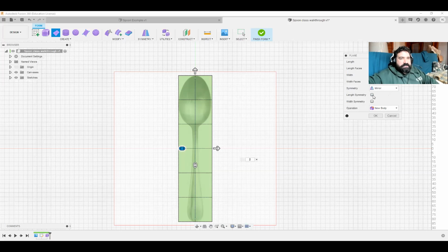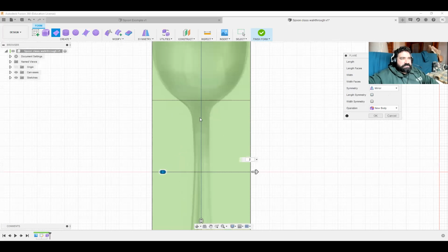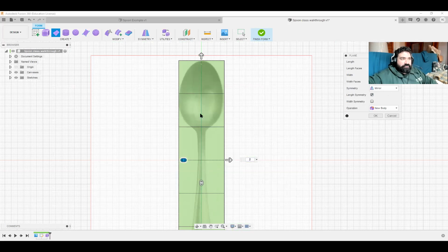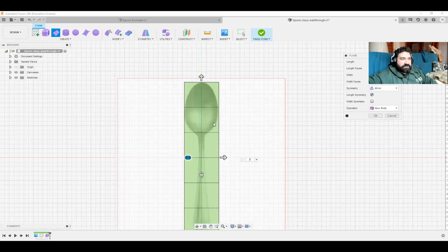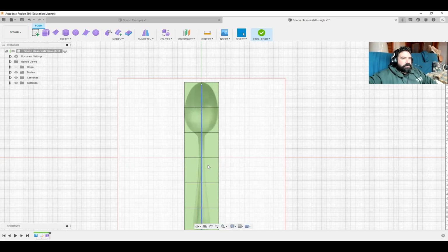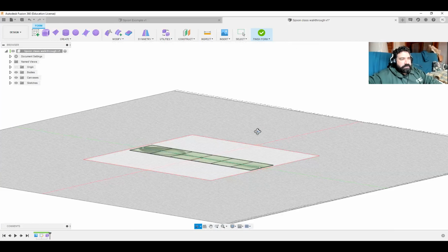The selection there is length symmetry. When you select that, if I zoom in close, you can see that center line is just a line like anything else. If I select length symmetry, that becomes a dotted line, just like a construction line, because what that's showing is now it's green. It's showing that's the symmetry. Across that line, one side will do to the other. Cool, operation is good. Hooray. Now we have a singular plane to work from.